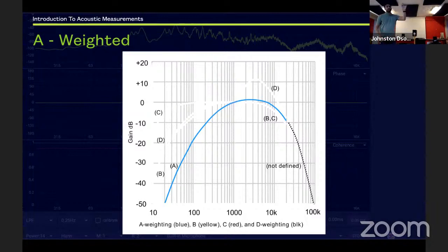So you might have seen in certain equipment, whatever dB SPL, and then you'll have a parentheses. In the parentheses, you'll have an A written there. That means it is dB SPL A weighted. In most cases, we use A weighted scales only. I have an SPL meter here. I'll show you how that is done in just a bit.